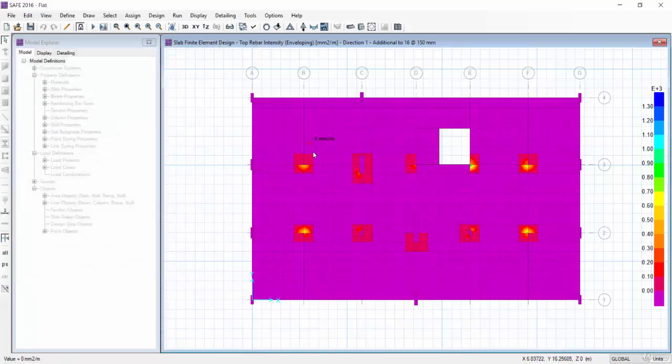Okay, also in solid slab, the same method of design, but in solid slab we have interior beams, so we need to design these beams like we designed the beams in the ribbed slab type 1, and the same method, the finite element method, to design the solid slab. So we don't have to design the solid slab again because it is the same method as the flat slab.